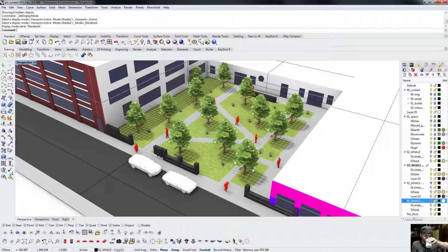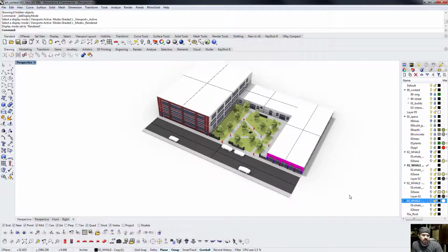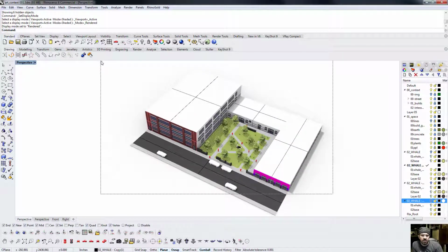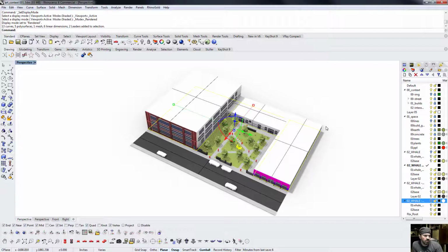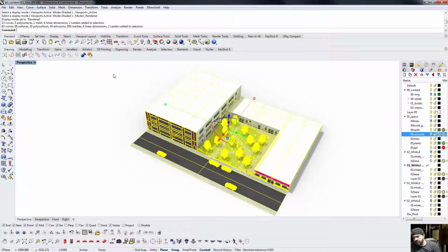Anyhow, the one thing you need to know is that everything needs to be at 0, 0. Unfortunately, there's no ability for it to lock in spaces, or for changing the XYZ axis component inside Twinmotion.